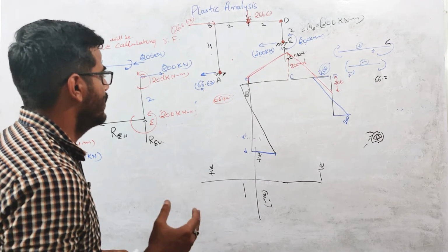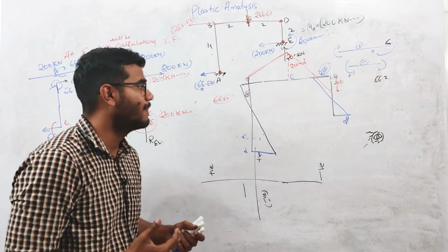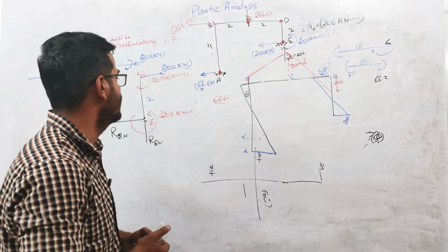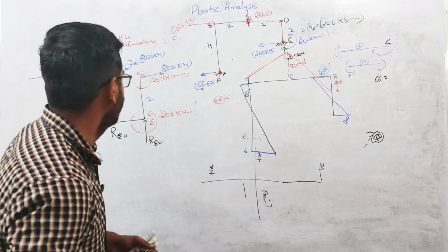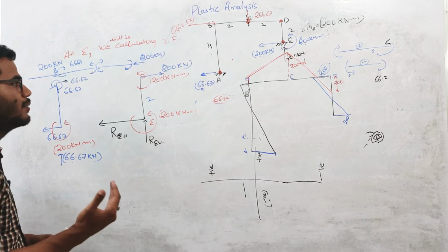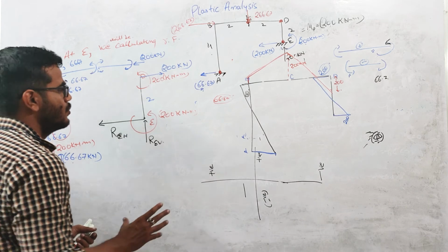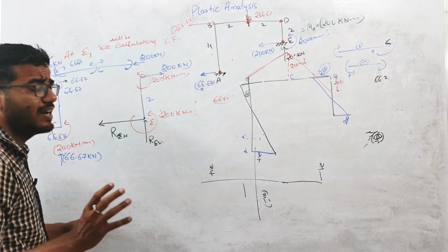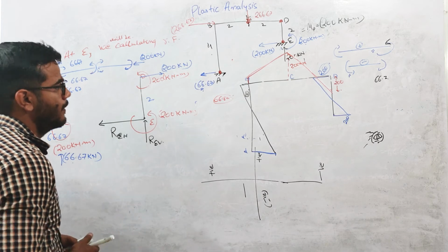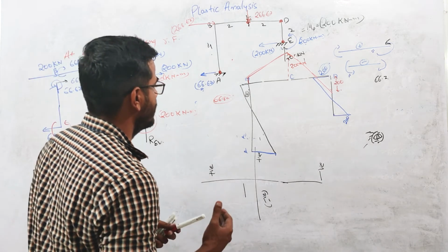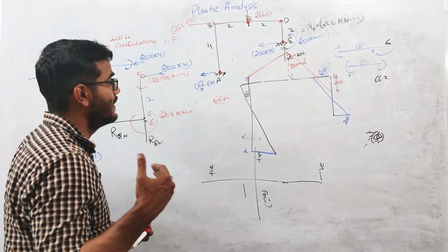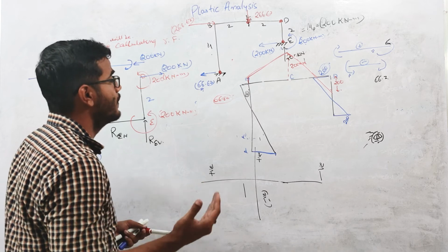So guys, I have discussed this thing in detail, how to draw the bending moment diagram. So if you still have any doubt regarding this, you can write in the comment section. Okay. And one more thing, in the books, you have seen that bending moment is drawn on the compression side, bending moment is drawn on the tension side. So this I have already told you about the deflection diagram, how this frame will deflect. So you can draw that, you can understand at which portion there is compression and which portion there is tension. I did a detailed discussion in slope deflection method, right?